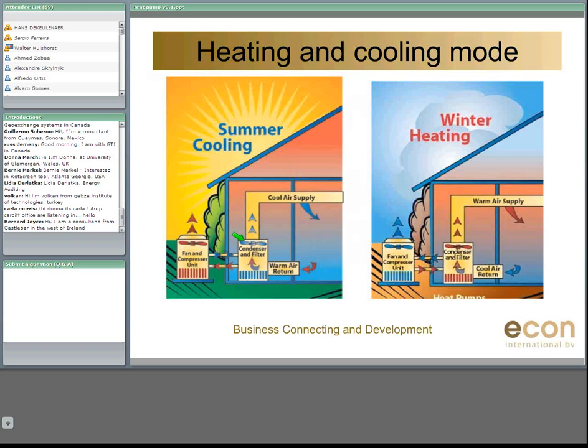In the cooling mode, the heat pump works similar to an air conditioning. It uses an evaporator to absorb the heat from inside the house and rejects that heat outside at the condenser. So here you collect the warm heat and then go to the condenser, and here the warmer heat is getting out. The refrigerant is flowing through this cycle over there, and also through, of course, a condenser and a compressor which you have outside.